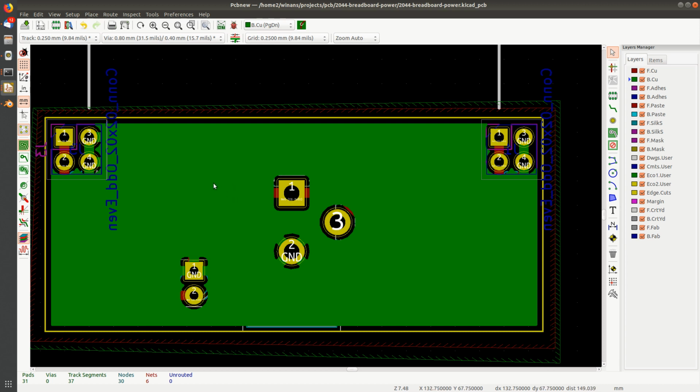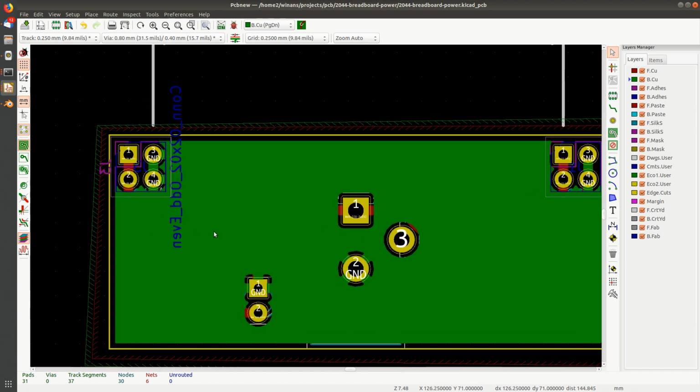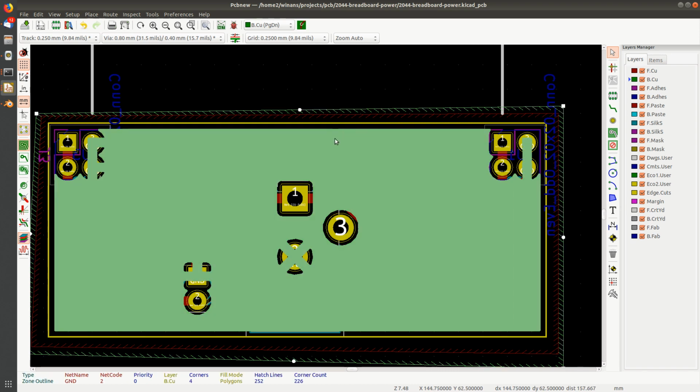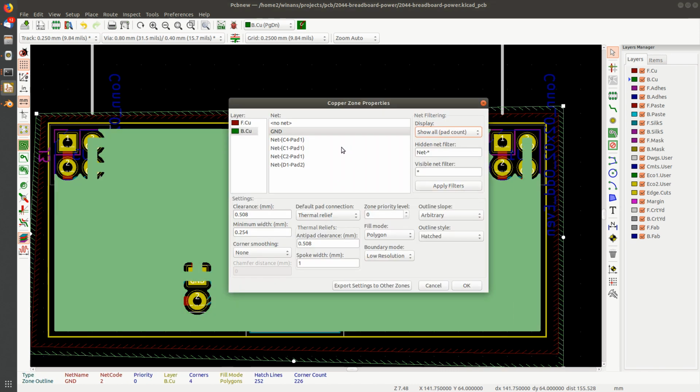Other than when I mentioned that, when you put this connector down, some manufacturers can't make slotted holes. They only want to drill them. It's cheaper to make drill holes than slotted holes. So even if they can do it, you might avoid it for cost. What I'm getting at is the other settings in the filled patterns. I just had to edit again. These clearances and the distance from the edge of the board matter.